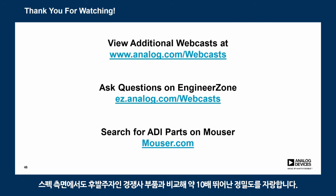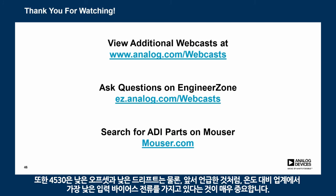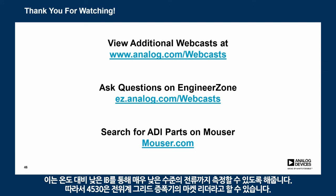In terms of specifications, it has about 10 times better precision compared to the next leading competitor part. It has really low offset and low drift. I think I've mentioned time and again that the 4530 has the industry's lowest input bias current over temperature, and I think over temperature is the key. It has really low IB over temperature that allows you to do really low level current measurements. So definitely, the 4530 is the market leader in electrometer grade amplifiers.